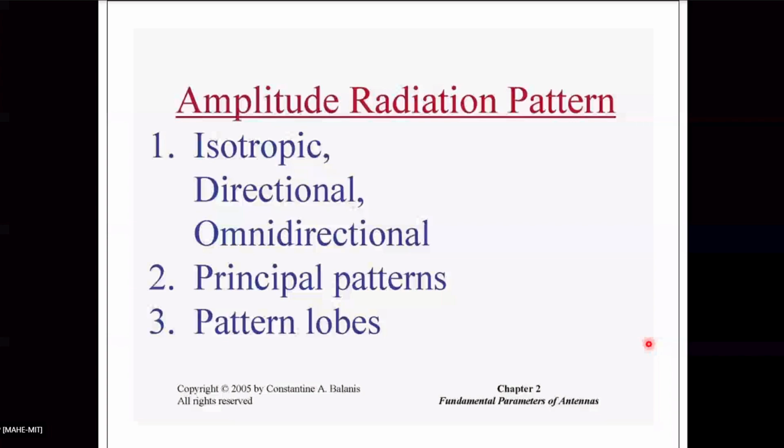It will be spherical. When you plot it in two planes, when you plot it in theta is equal to constant plane or phi is equal to constant plane, what do you get? Theta is equal to constant plane is the horizontal plane. Are all of you able to visualize that? When I explained the coordinate system, I told you how it is the horizontal plane. So, what is the pattern of an isotropic source in the theta is equal to constant plane?